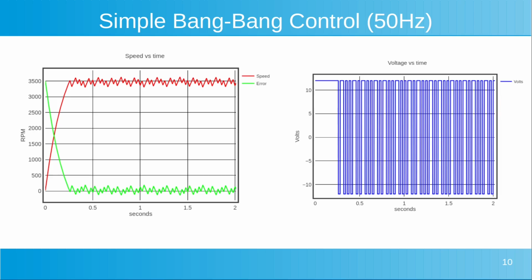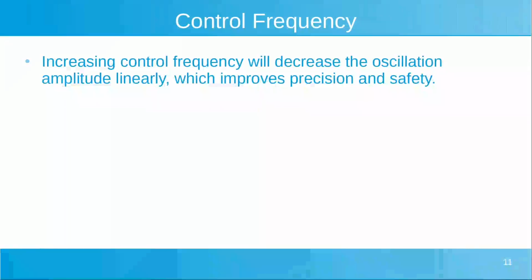Also, note that the oscillation is biased down somewhat. This is due to both friction and the DC motor mechanics. As I mentioned earlier, when it drops to minus 12 volts, that's producing a lot more negative torque than the motor produces by the plus 12 volts, just because of the difference in speed from where the motor is spinning to where it wants to be.